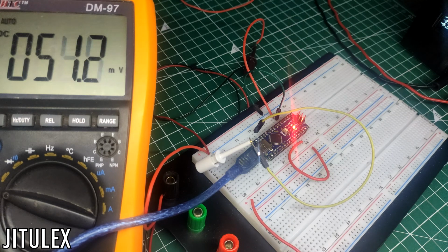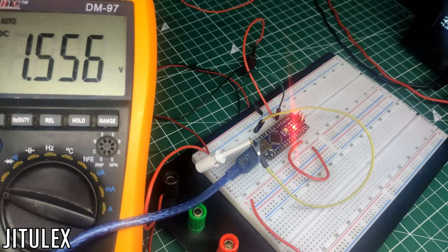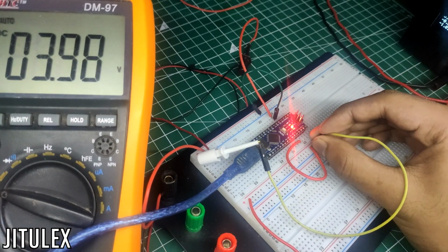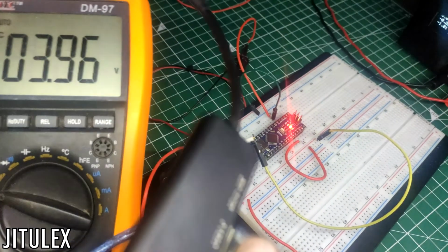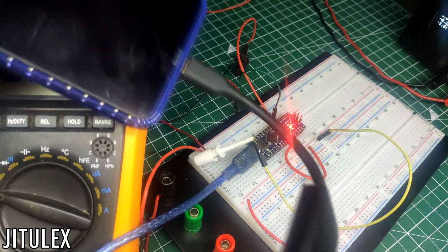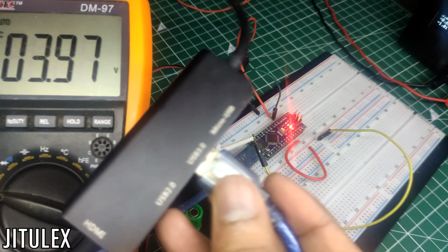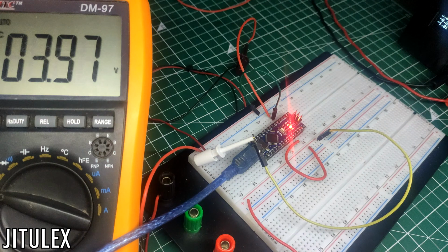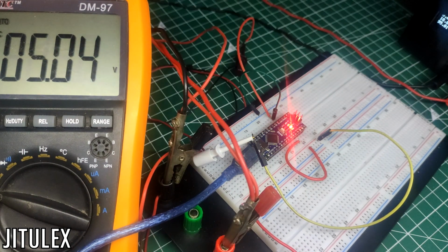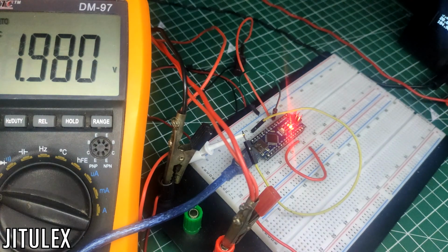Now when I went ahead to practically test this, I noticed the value was way off. So I measured the input voltage and found my problem. Most of these Arduinos run at 5 volts and some at 3.3 volts. And I had the 5 volt one. But I was powering it with my USB hub connected to a phone, which was not able to provide enough power to the Arduino somehow. So I connected my power supply to provide 5 volts and tested it again, and it was accurate.